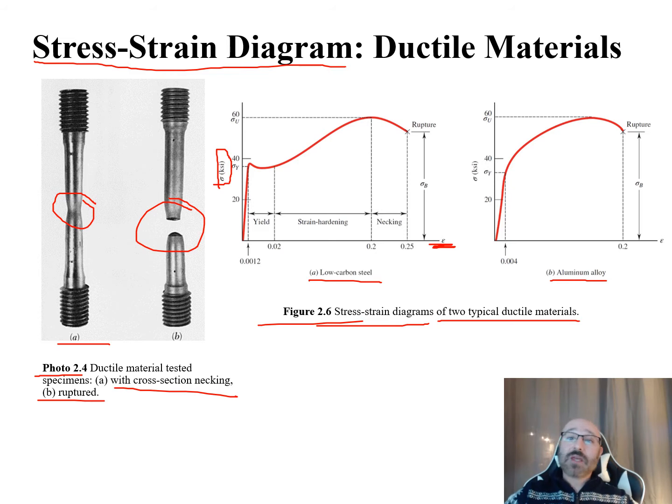Now a lot of times what you may see live on the screen for a lot of these is force versus displacement. So just make sure that you're taking a look at the right things, and you're not trying to calculate things that you need a stress-strain diagram for, like your modulus of elasticity, off a force-displacement diagram. You do the calculations and form the right graph before you start gathering some information off it.